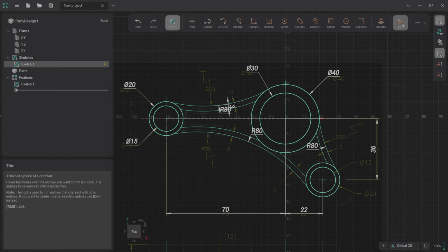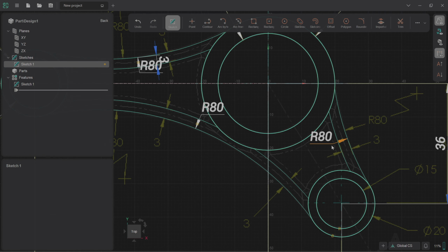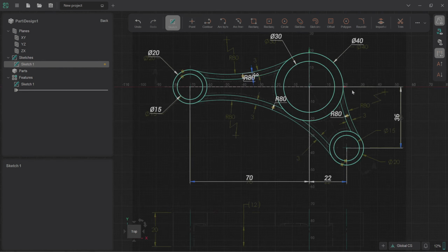Anyway, so we turn off the trim tool, and we now have our part pretty perfectly described. It's everything that we want it to be. So let's take a look at what we need to think about for the extrusion parts from here on out. If we have a quick look at this, just to make sure there's no extra details we need to be aware of, we can see there's a whole bunch of filleting that's described, but we don't have any of the radii dimensions listed yet.